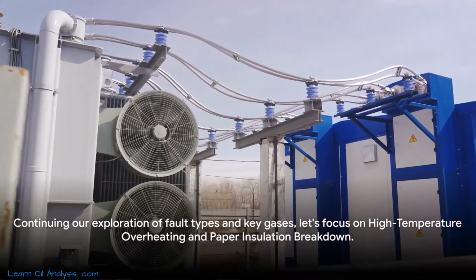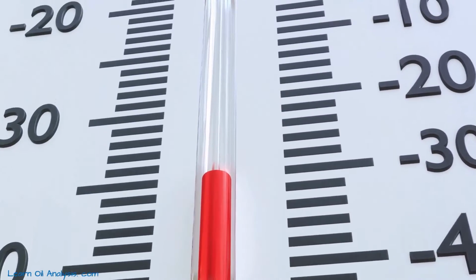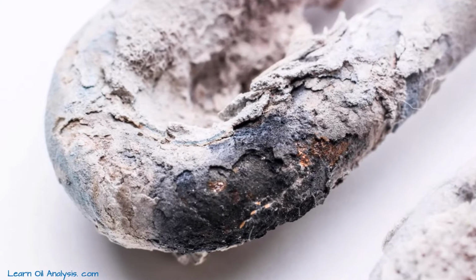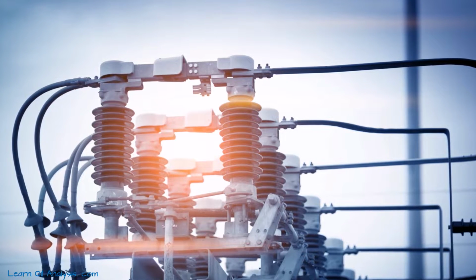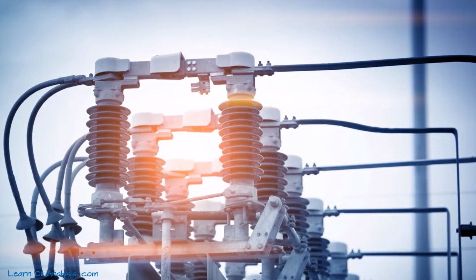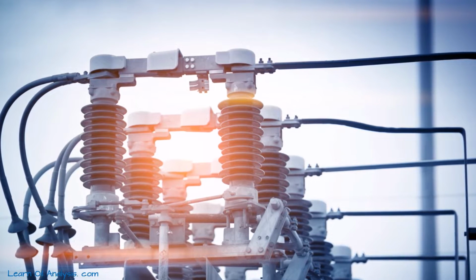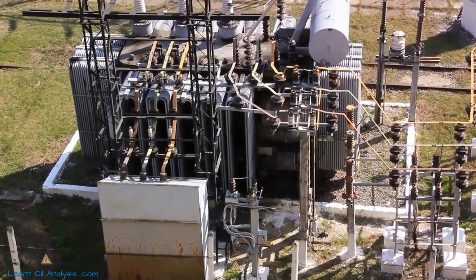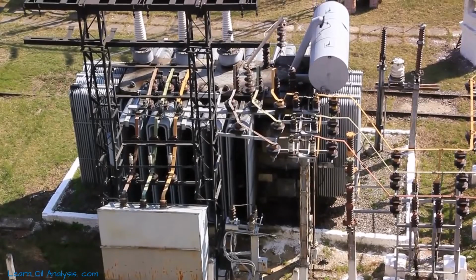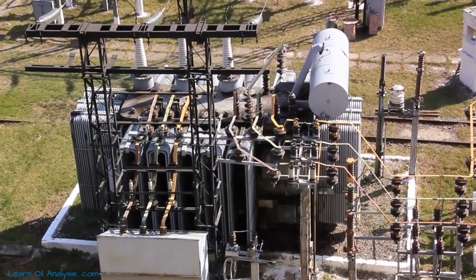Continuing our exploration of fault types and key gases, let's focus on both high-temperature overheating and paper insulation breakdown. At the heart of our discussion is high-temperature overheating, a common defect that can seriously compromise a transformer's performance. When temperatures rise steeply, often due to overloading or lack of efficient cooling, fault gases are produced. They are classified according to the temperature they form at, typically grouped into less than 300 Celsius, 300 to 700, and greater than 700 Celsius. In a high-temperature fault, ethylene is produced, a double-bonded molecule indicating higher energy processes.